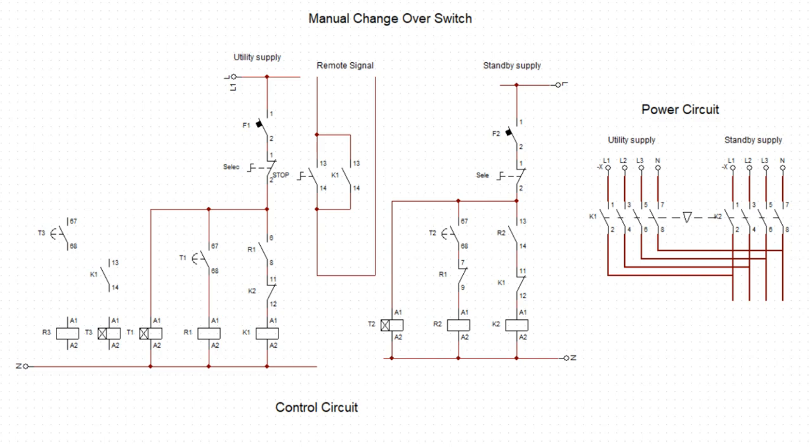We are going to feed this on-delay timer through here and through here. So when this power is on, once here gets energized, here will close. Once here closes, power comes to the timer delay for shutting down. It will start counting. When the time elapses, the contact here will close. Look at the contact.